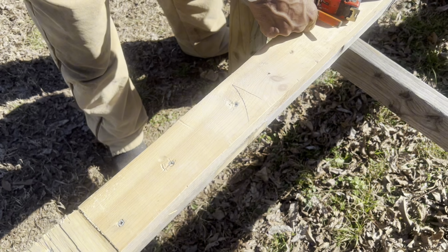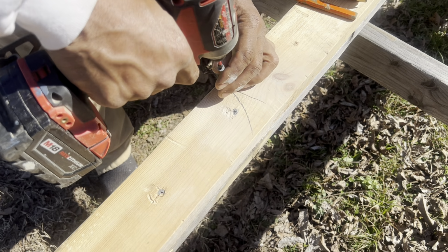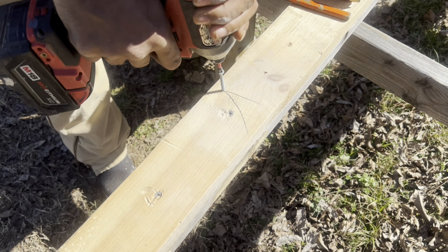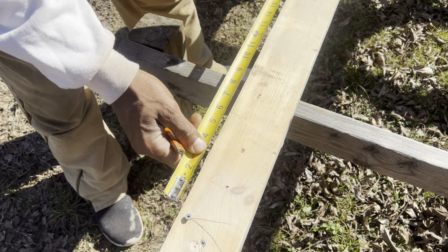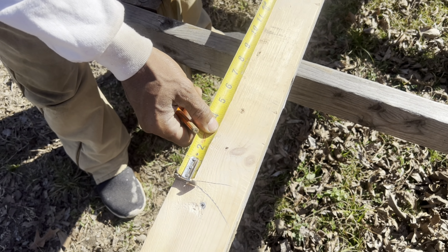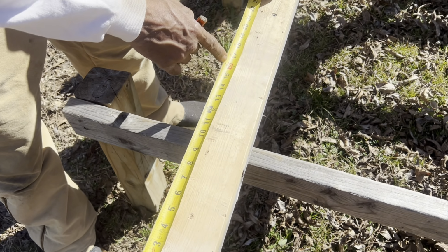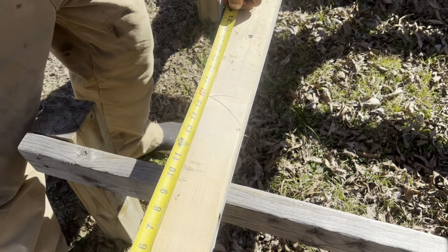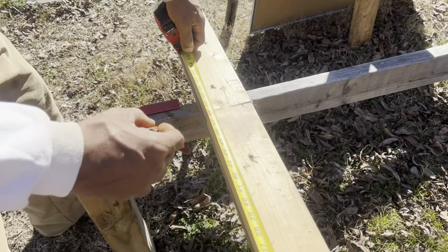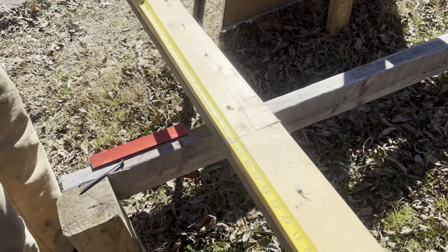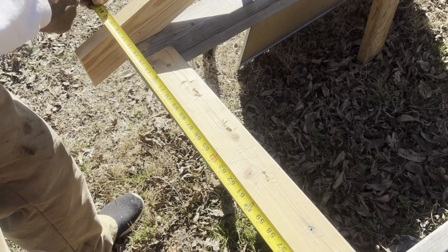Now I get me a fastener, whether it's a screw or a nail. And I also want to mention, when you're framing, you want to use nails, okay? Because nails work better when you're framing. Now I take my tape measure and hook it on my 15.25. Now I can lay out 16 inches on center for my rafter. You see it's in red right there? Put a crow's foot, 16. Keep going, 32. Keep going, 48. Let's go, 64. Okay, and this last one right here is going to break right there.